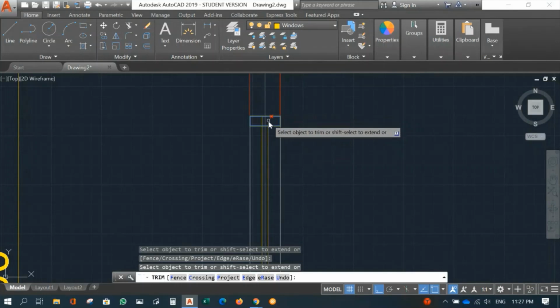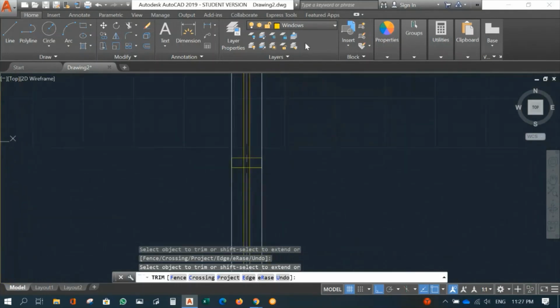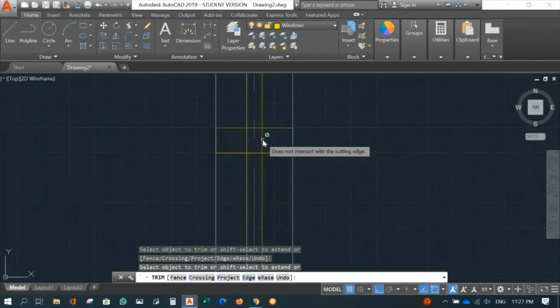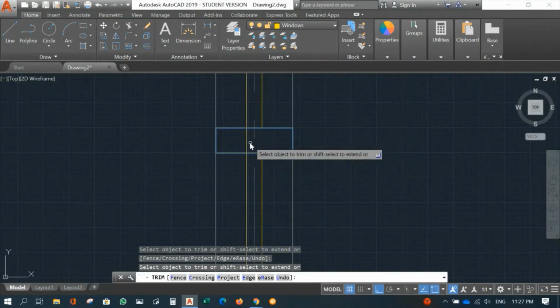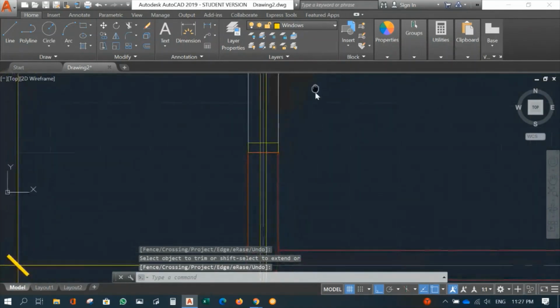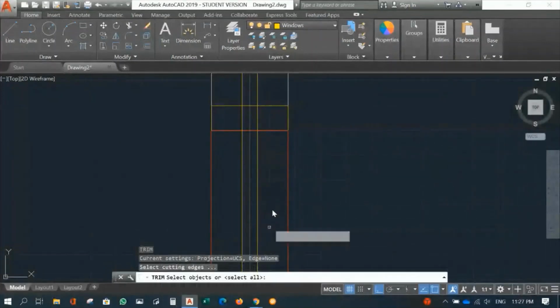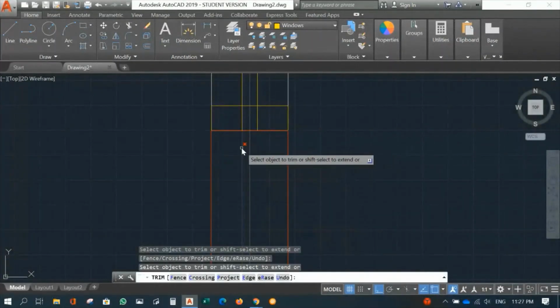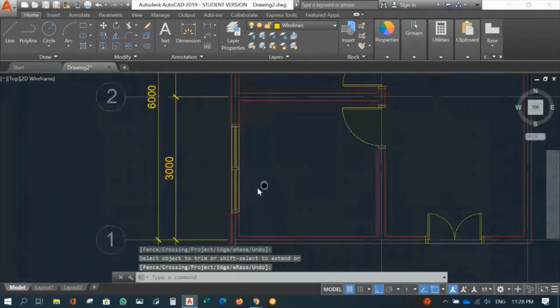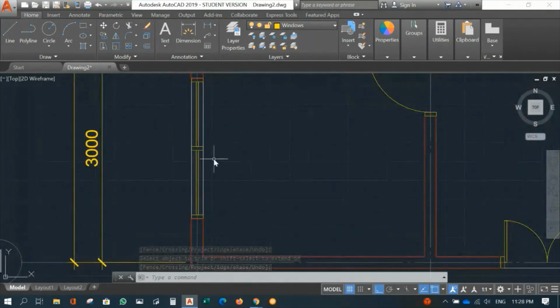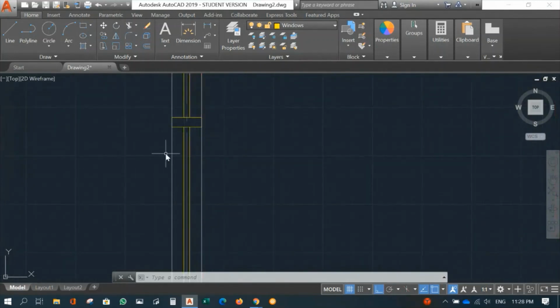Trim, trim, trim, trim, right? So this is a trim again, space bar, trim and trim. This one here, so trim again, 1, 2, 3, 4, and there you are, right? So this is windows, created windows. So the layer is actually yellow. However, the left and right outside here must be white colors or 0.2 pen.